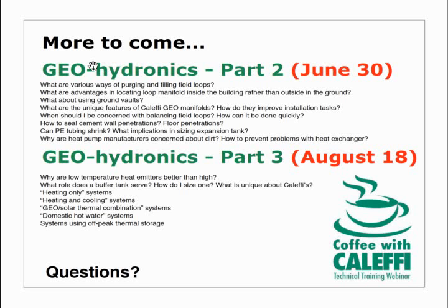Because, again, it just shifts us to that lower COP and lower capacity. So it's a trade-off between the cost of a larger heat exchanger versus the performance degradation due to the fact that there is a heat exchanger in there. But I'd suggest a starting point of no more than 5 degree Fahrenheit approach temperature difference on that heat exchanger.